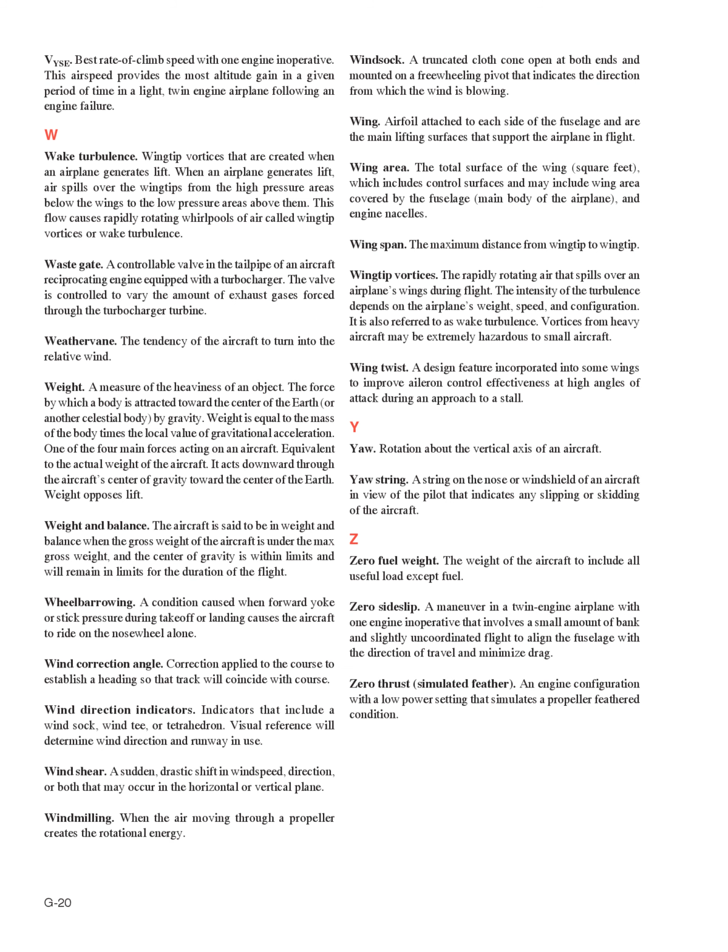Weight and balance. The aircraft is said to be in weight and balance when the gross weight of the aircraft is under the max gross weight, and the center of gravity is within limits and will remain in limits for the duration of the flight. Wheelbarrowing. A condition caused when forward yoke or stick pressure during takeoff or landing causes the aircraft to ride on the nose wheel alone.